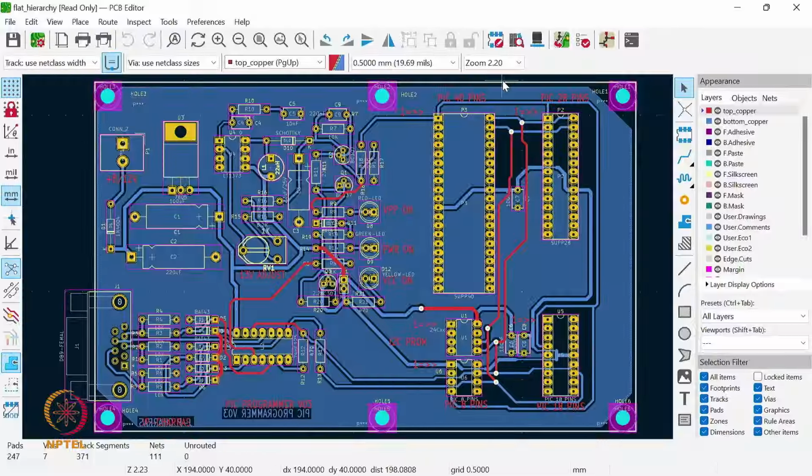So we need to know all these parameters, because we need to create our PCB so that when the PCB is manufactured, we can put the BGA package on that socket, on that PCB, and it should exactly align with the package.